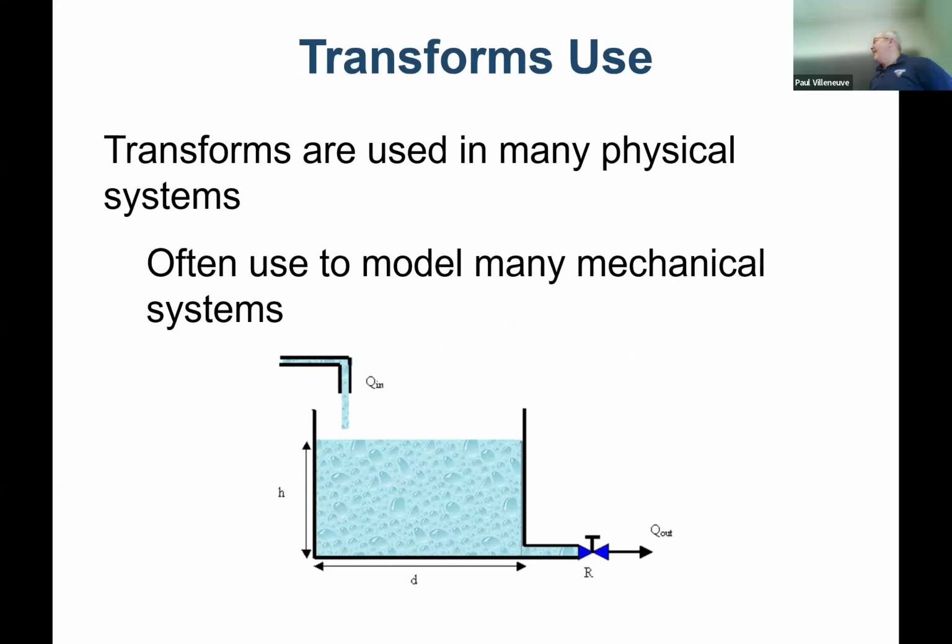So here's the tank system that I talked about, and we're going to see how that's modeled as a capacitor. We have the height of a tank, and sometimes that H term is not called height, it's called head, the head of the water, which is how high the water is over an output port. They talk about head more in hydroelectric facilities. You've got water filling in, and then an orifice or valve with an orifice that's limiting the flow out. Isn't that exactly like a capacitor?